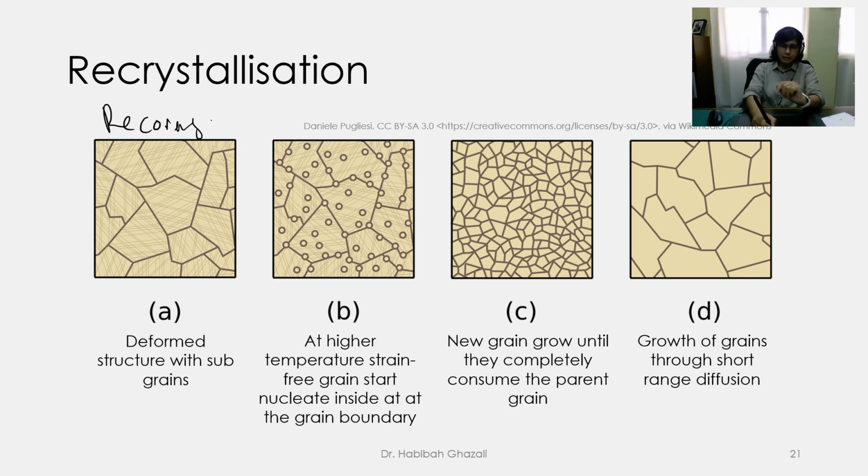So now we have this microstructure, which is equiaxed. It has approximately the same dimension in all directions. So this material is now going to be isotropic. Initially it was anisotropic, but after this recrystallization process, it becomes isotropic. And the recrystallization process needs time. Diffusion needs to happen over time. So depending on how long you leave it at higher temperature, diffusion will keep going.